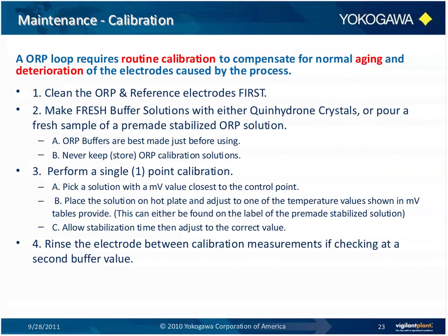It's good practice to note that if a span of 150 millivolts is found between the first solution and the second solution when you're using a quinhydrone buffer solution, which we'll explain in more detail later, or a span of 30 millivolts if you're using pre-made solutions, then the platinum and gold measuring electrodes are considered clean and can be put online. Outside of that tolerance, they need to be re-cleaned and recalibrated.